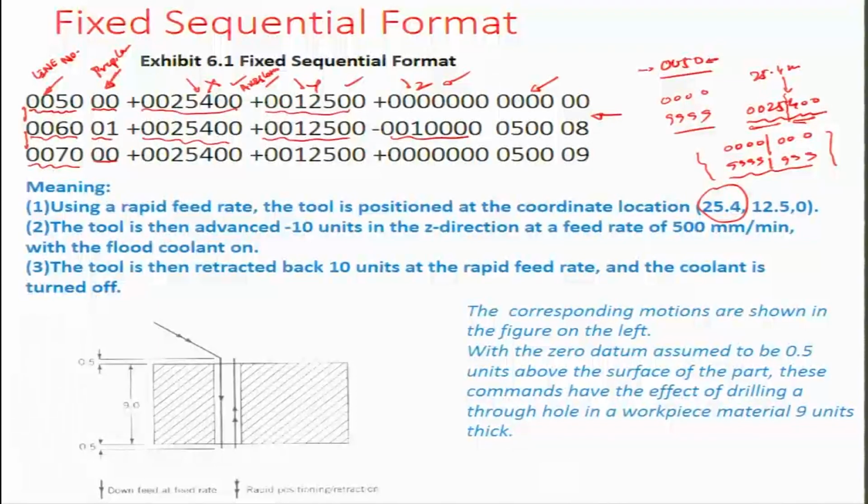For example, it could be the spindle on off or the coolant on off, or maybe something to do with the feed rate, RPM, etc. So this could be recorded as the feed or the speed command, and these are some other operations, for example related to the coolant or any other operation which are important yet not the main operation, and these are known as the miscellaneous commands.